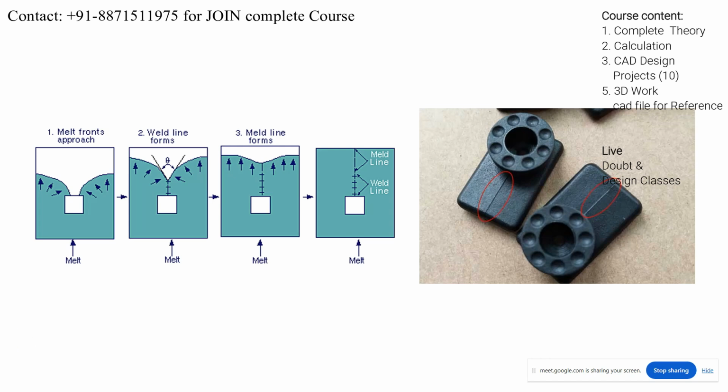Both are weld lines, right? Both, yes, but the melt line has more strength compared to the weld line. Because for example, if a weld line is produced there, the component can break from the weld line during operation, but a melt line has a strong bond into the surface, right? That's the main difference between the two. So basically we have to predict this type of weld line or melt line from the software, right? We should predict from there.